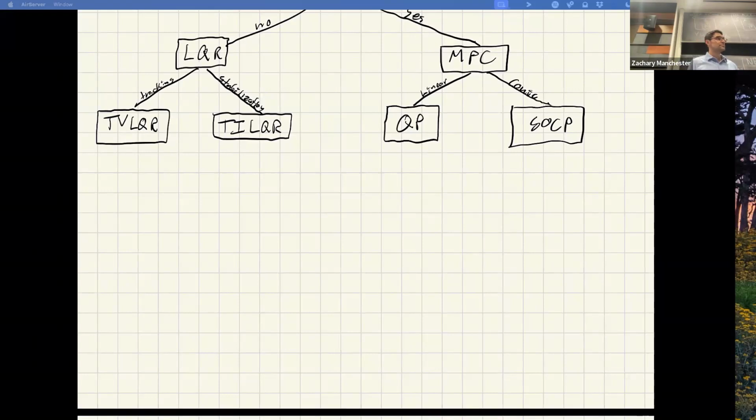So then people talk about domain randomization. I'm just referring to linearization. No, that's a bit more subtle. What they're really doing is a sort of random sample-based version of robust control. And there are linear analogs of that. There's an entire theory of linear robust control. What that's really getting at is errors in the model. So in the linear context, that would mean you have an A and a B, a linear system model, but there's uncertainty in the A's and the B's. And maybe it's stochastic or maybe it's bounded uncertainties, right?